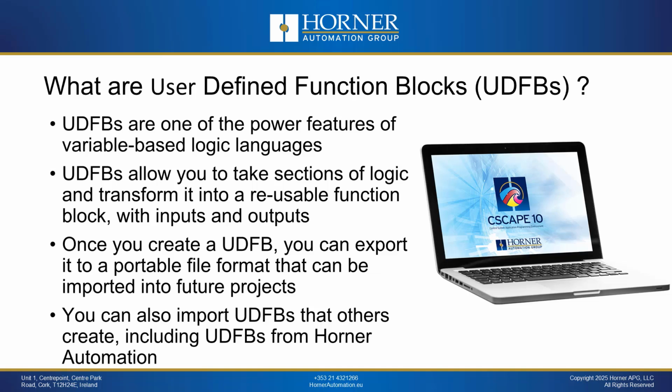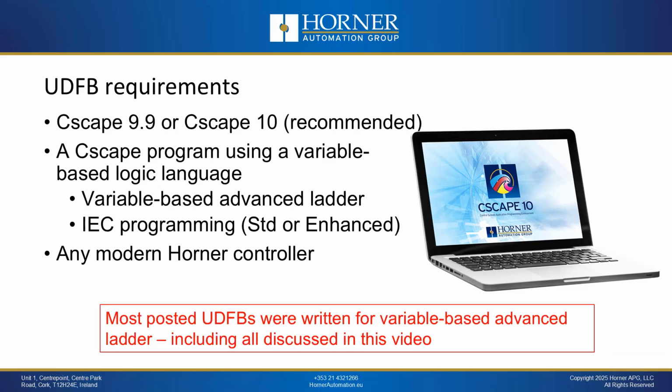So what are user-defined function blocks? User-defined function blocks are one of the power features of variable-based logic language. UDFBs allow you to take a section of your logic and transform it into a reusable function block with inputs and outputs, just like a regular function block in Cscape. Once you have created a UDFB, you can use it multiple times in your project. You can then also export it, and in the future, you can import it into a new project and use it multiple times in that project as well.